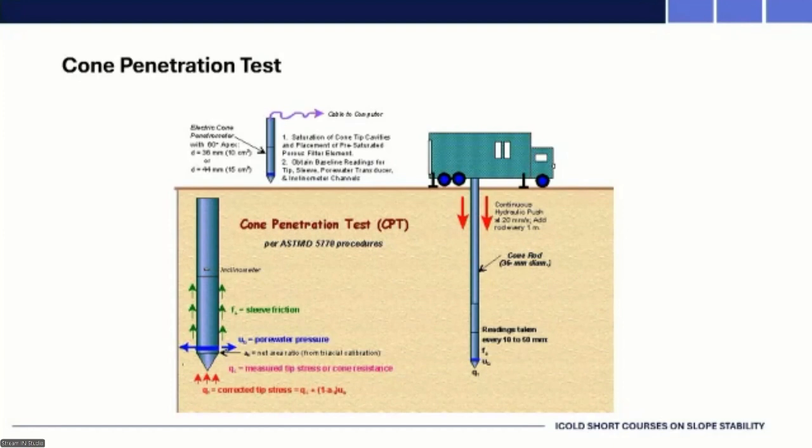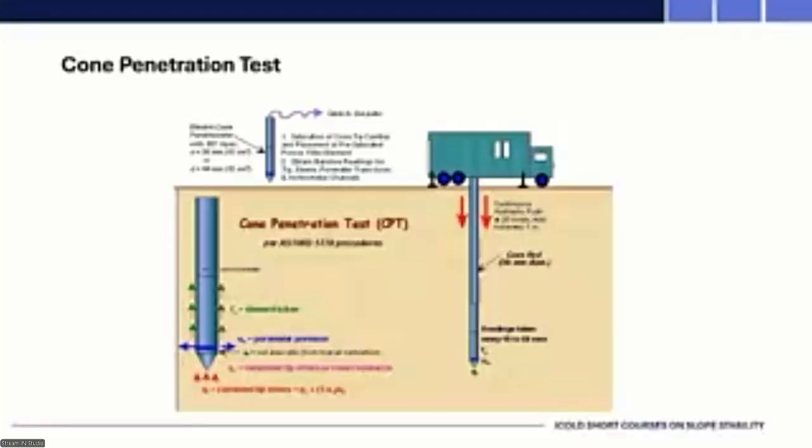So at the tip, you've got this resistance, that's the tip resistance. You've got the arrows on the side of the shaft, that's the sleeve friction that you're measuring, and then you've got the pore pressure. Now, there was a lot of debate in the early stages about where to measure that pore pressure. We've settled on just behind the shoulder, that blue, and hopefully people can see blue. That's where we measure pore pressure, and it's called the U2. It's got nothing to do with Bono, it's just the position where we make the pore pressure measurement. Just note that we're not measuring the tip resistance and the sleeve friction at exactly the same depth. There's a bit of an offset. Always keep that in mind as well.